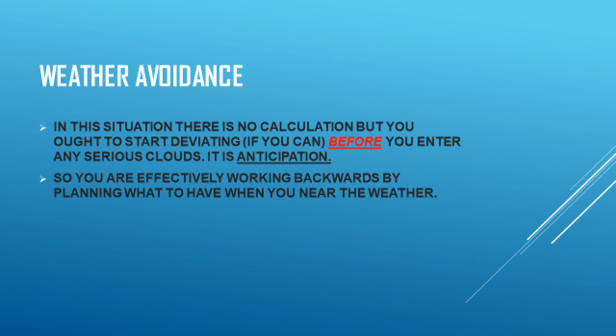So if you are at night, you can only rely on that display of yours, and well before you even approach it, you just steer using heading select left or right, or you can descend or climb if you're at a lower level. Remember, you cannot climb more than your service ceiling of 25,000 feet, for example.